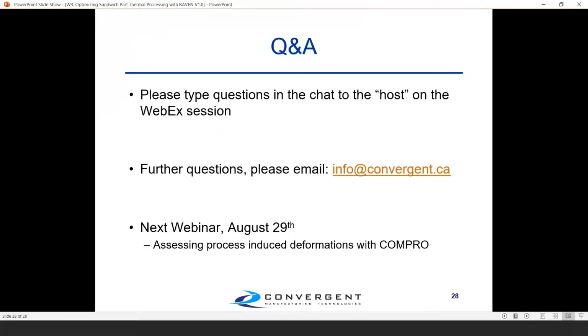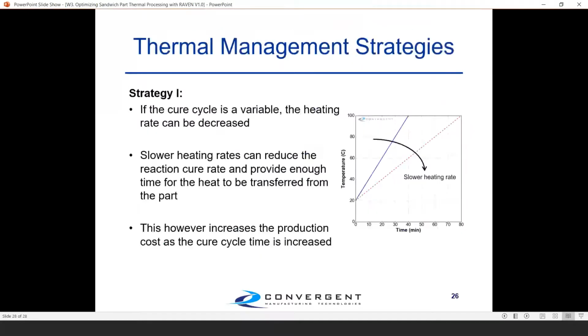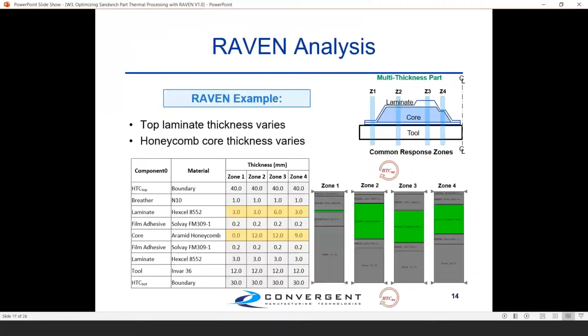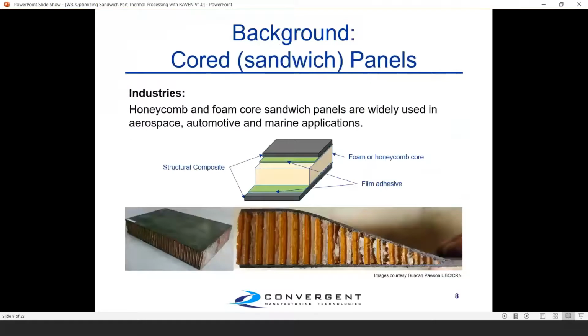Okay, so we have our first question here, and it is, how do we deal with the tapered edge of a honeycomb core? Right, okay. So I'm going to go back up to the start of the presentation where I had that picture of the honeycomb core here. So I guess this is really how would you address this zone on a real part, which would typically taper down like this. And so ultimately, we don't actually address that in the 1D analysis.